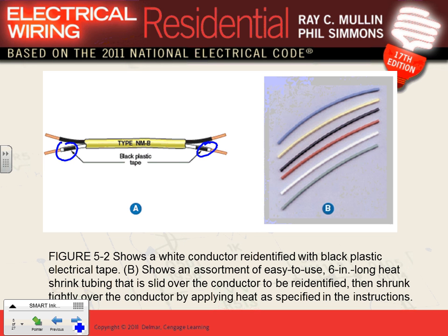The other application for it is supply power to the switch from 14-2, right? You take a 14-2 cable here, you re-identify the white, feed the switch with the white as a supply, and the black goes all the way up. Why do they allow you to do that? Safe on copper. Now, with the change that happened recently, you're going to kiss this one goodbye now, right?